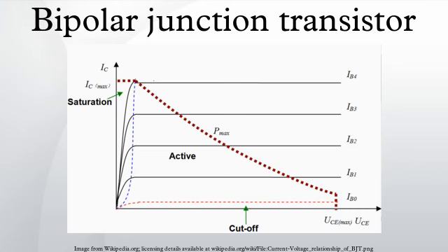Small signal models, hybrid pi model. The hybrid pi model is a popular circuit model used for analyzing the small signal behavior of bipolar junction and field effect transistors. Sometimes it is also called Giacoletto model because it was introduced by L.J. Giacoletto in 1969. The model can be quite accurate for low-frequency circuits and can easily be adapted for higher-frequency circuits with the addition of appropriate inter-electrode capacitances and other parasitic elements.